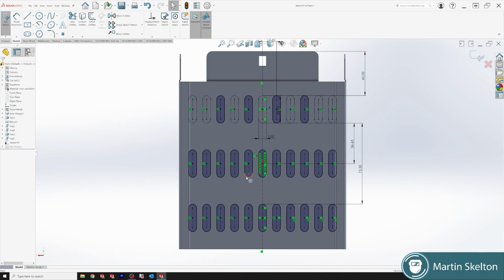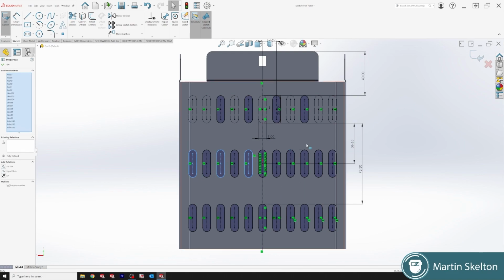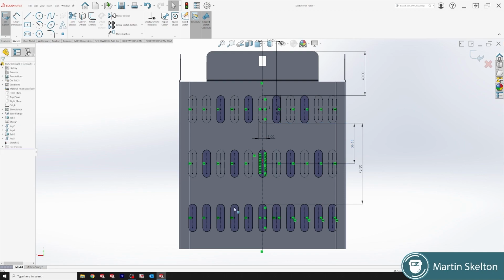That's one row. Next row has a center. So we're holding the shift. We know that this one, and the end one are not required. So that's the end one here. This one, and this one. And likewise again, because there is construction line and solid line, you click it off construction at this side. Now everything is solid, click it back on, everything is now construction.